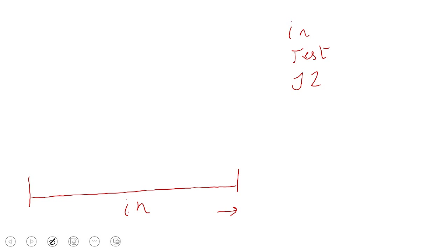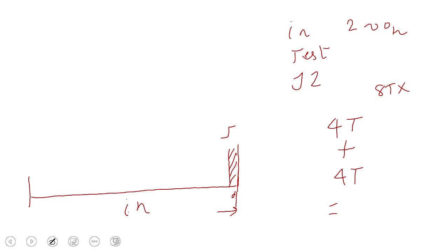Such a similar thing happens: the in instruction is reading the input from this address at almost exactly the end of its cycle. And the key press also happened exactly at that moment, and you didn't wait for that in cycle. So you didn't wait for those 80 cycles, but you are now going to do a test, 40, plus jump 0, another 40 cycles, which is just 80. So this is the best case.